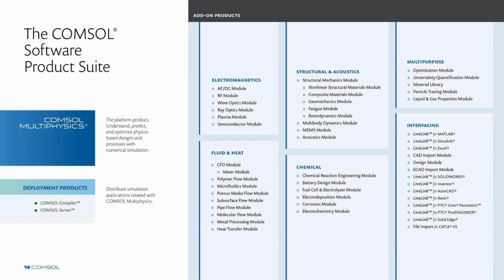And also there are so-called interfacing products like the LiveLink products. One of these is LiveLink for Simulink. So if you happen to investigate a PID controller of a battery management system, you can use Simulink for that purpose and other tools. And you can include a high fidelity finite element model of the battery pack itself. In this sense, you can create a so-called co-simulation. And that's what we are going to discover today.